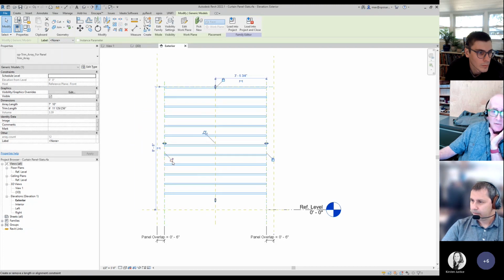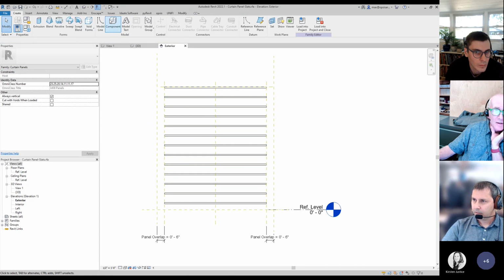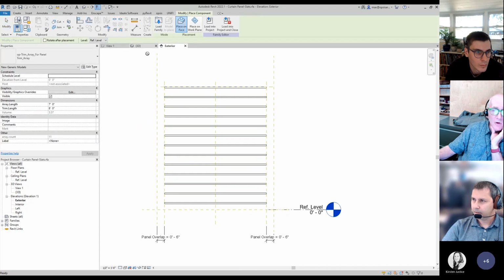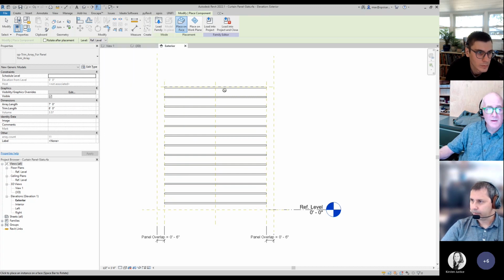That's a constant gotcha: the cross through won't let you place it because you have the wrong mode selected at the top, for anybody that wants to try this. That's a good place to look when you get something that you can't put in there but you think you should be able to. Since there are no planes like this little diagram shows, you can't place it anywhere. The family is empty, so you want to pick a work plane to be able to set that.